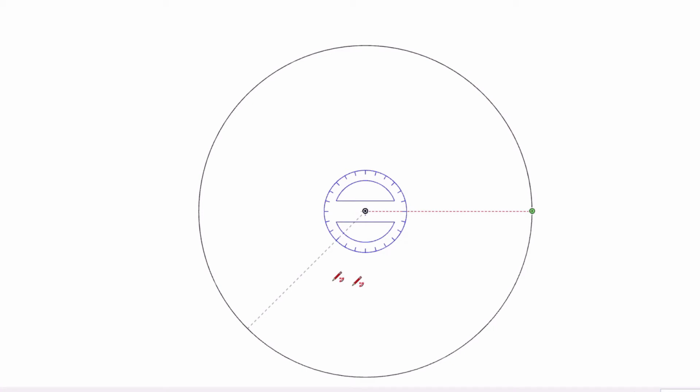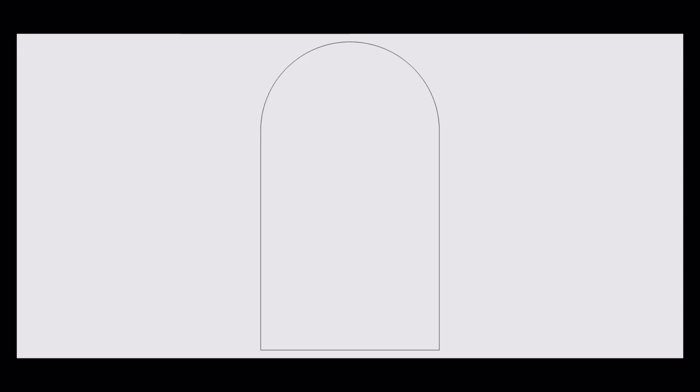It's difficult to record the shape of curves with a tape measure. However, the radius is the only piece of information necessary to describe the shape of a curved path. The radius is a straight line from the center to the curved path or circumference. While the exact center is not normally easy to locate, the dimension of the radius can also be calculated from other measurements which are easy to take.